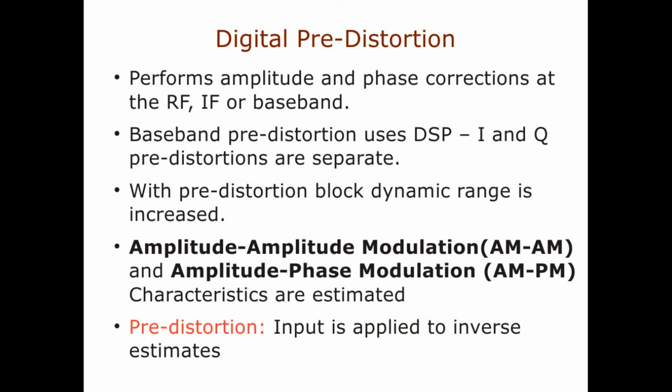So a very good technique by which you can determine this is by giving some reference signals and identifying what are the corresponding amplitude as well as the phase distortions happening for each and every individual frequency, and then applying an equalizer sort of mechanism where these are taken care of, and hence the overall system is free from all sorts of phase shifts and amplitude shifts.